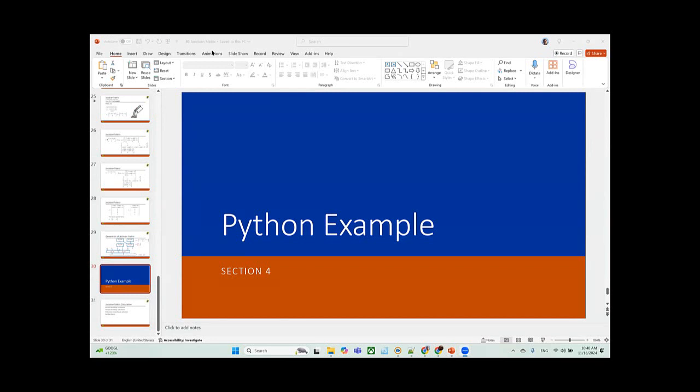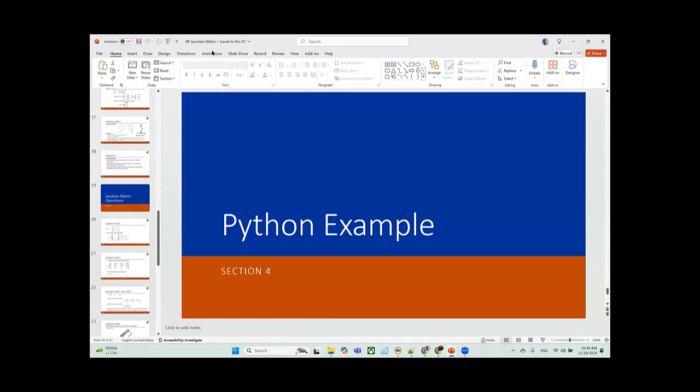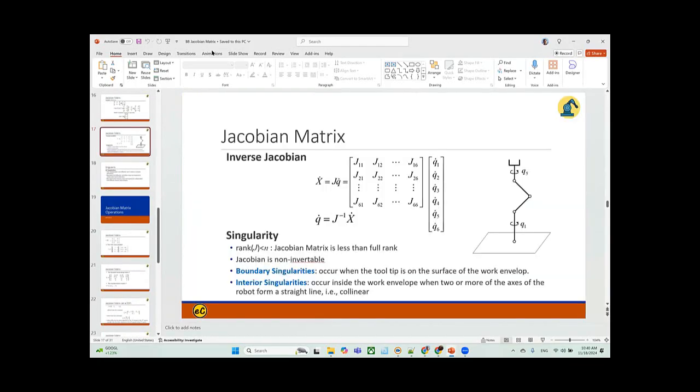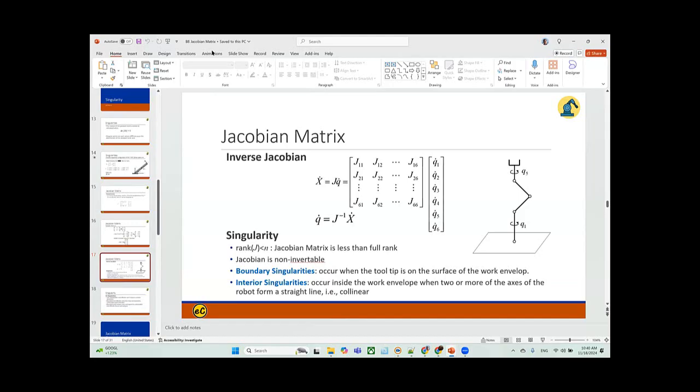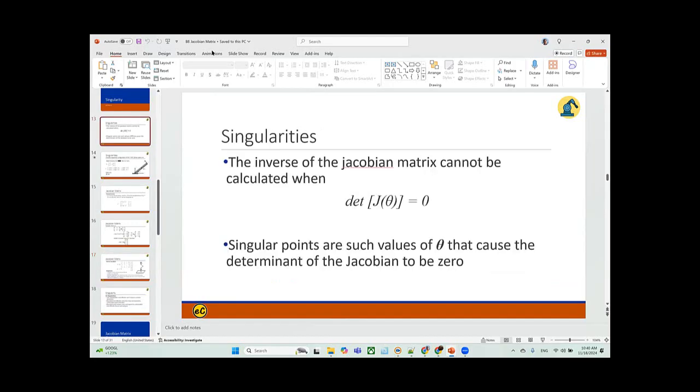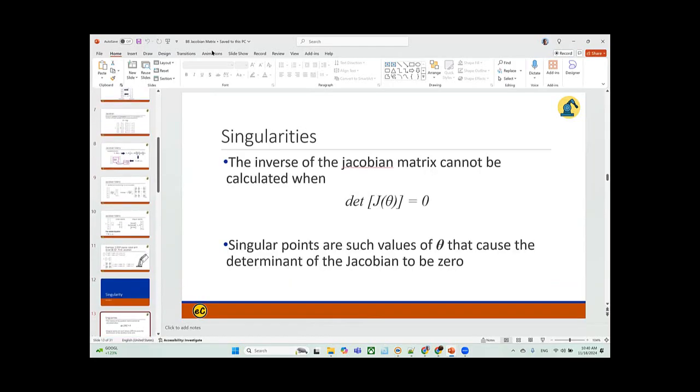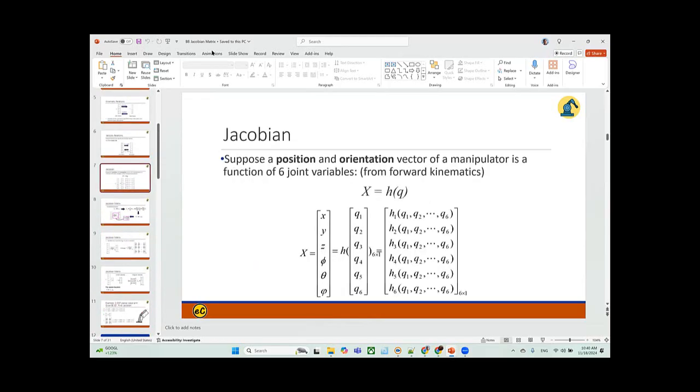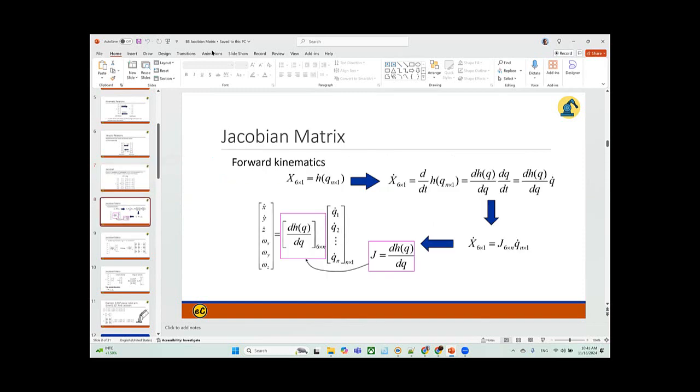So this, you have to go through the derivation of the Jacobian matrix once and really understand what is the purpose of doing such kind of calculation. Okay. This is the inverse Jacobian. Forward Jacobian, you have to understand what is forward Jacobian first. Okay. It's coming from here. You set up the system equations for all of the joint points versus the XYZ, the destination variable in the workspace, and you take derivative.